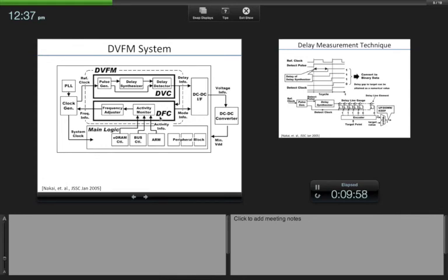So you have dynamic frequency control, dynamic voltage control. How is frequency adjusted? In a particular phase of operation, you just monitor the activity of various components in the chip. Embedded DRAM controller, right? There will be a controller to control the embedded DRAM, where you would make a request to fetch from the DRAM. So the DRAM controller will have an idea for, okay, now a fetch has come in this cycle. So you just keep track how many times a fetch or access request has come.